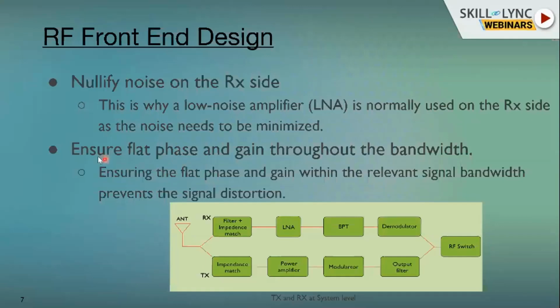At the same time, when I mention that we are going to design a 5G transceiver, it means that over the band of frequency, it is going to work on different bands. So it has to have flat phase. All these active components have to have flat phase and gain throughout the bandwidth.